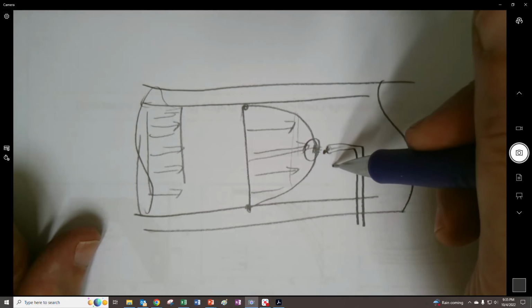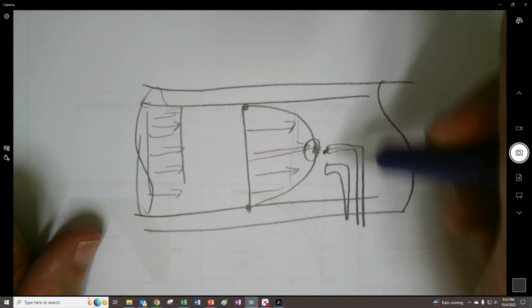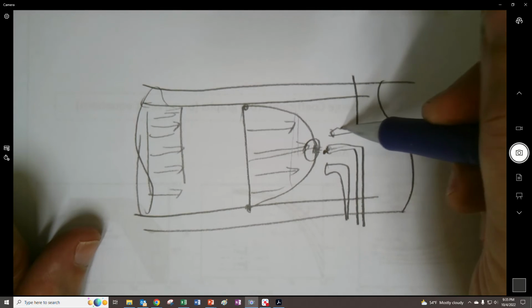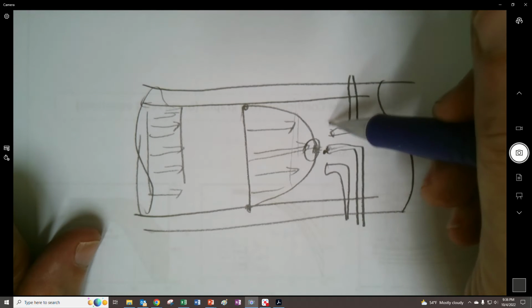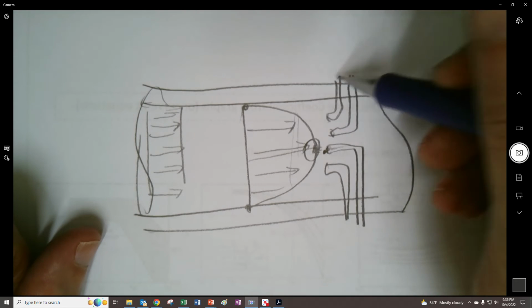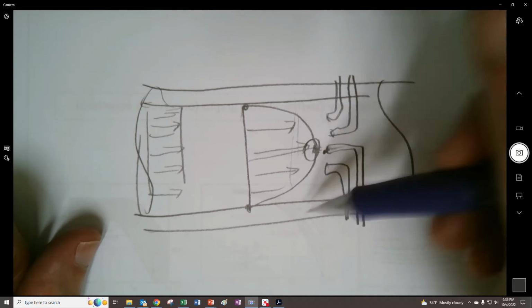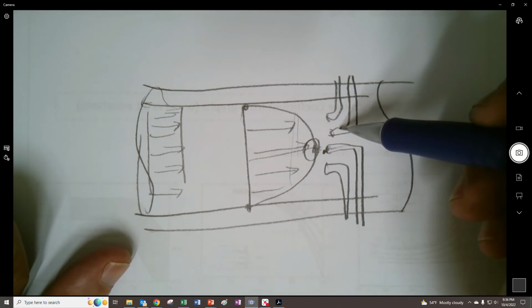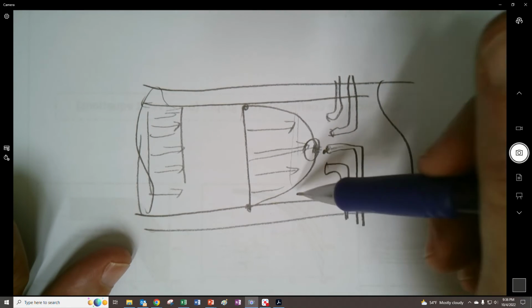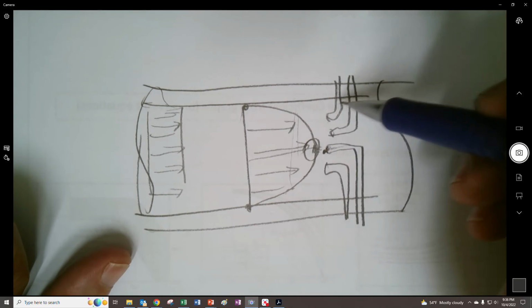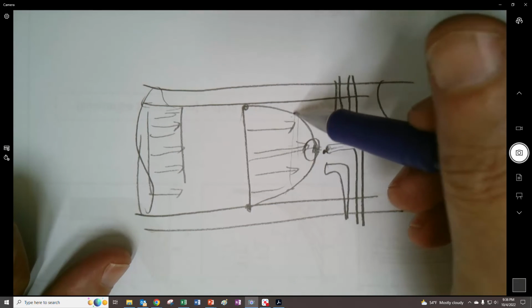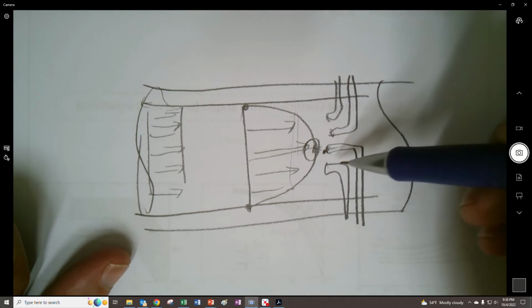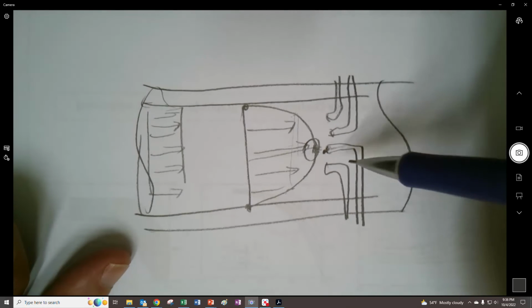What you could do is have multiple pitot tubes, instrument the thing, and capture what the velocities are, but of course the act of doing this will also influence the results. If these are small enough, maybe they won't be too bad. And you could maybe try to figure out what this velocity profile would look like if you were very careful in your instrumentation.